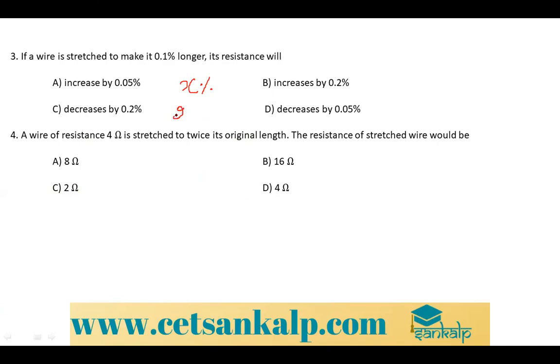Then the resistance will be increased by 2x%. Please remember in the exam, after stretching, if the length of the conductor is going to be increased by x%, then the resistance value is going to increase by 2x%. But you have to see one condition. It is going to be valid when x is less than 10%. If x is less than 10%, then you can apply this condition.